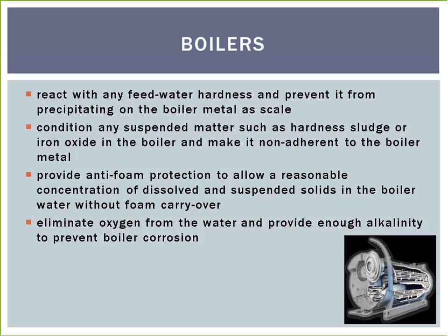Also, natural and synthetic dispersants, or anti-scaling agents, increase the dispersive properties of the conditioning products. They can be natural polymers or synthetic polymers. Also, sequestering agents, such as inorganic phosphates, act as inhibitors and implement a threshold effect. Oxygen scavengers, catalyzed or not, reduce the oxides and dissolved oxygen. Most also passivate metal surfaces.